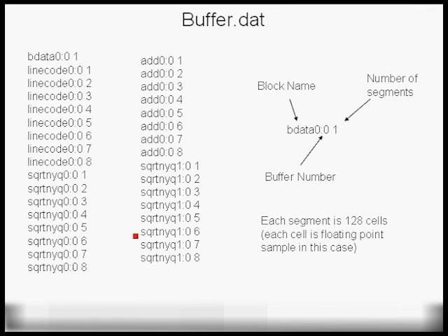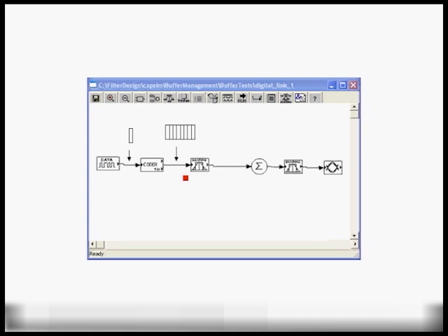We should note, let's go back to the diagram, the actual topology, that these simulations are very efficient because for every bit that's generated, we're generating 8 samples due to oversampling or multi-rate signal processing. However, each block that processes these samples, once it is visited by the kernel in order to do its execution, will consume all the samples on its input buffer and very efficiently process all those samples and output them on its output buffer.